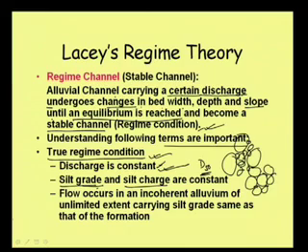And then what is silt charge? Silt charge means the volume of silt that is coming into this channel. Not only the size of the particle, but what is the total silt concentration, the sediment concentration in the water. The sediment which is flowing can be in suspended form, or it may be moving along the bed. So how much total sediment, as we were discussing earlier, that is the bed load and suspended load.